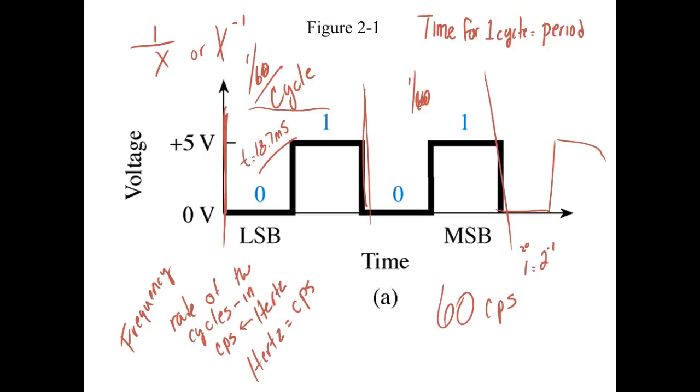You understand? So if frequency goes up, the time for the period goes down. They are inversely proportional, exactly inversely proportional. So if I go from 60 and double it to 120, my period goes to 1/120. If the bottom number goes up, the time goes down. So if I double the frequency, the period halves, which means I can take the reciprocal of the frequency and it will give me the period. The period is the inverse of the frequency.